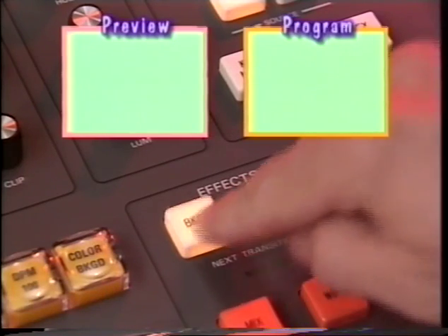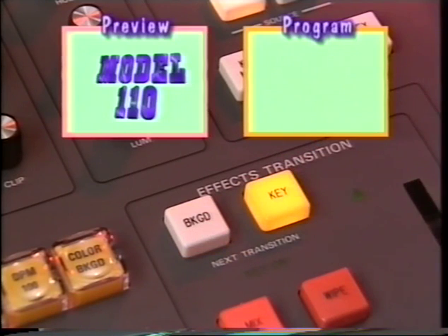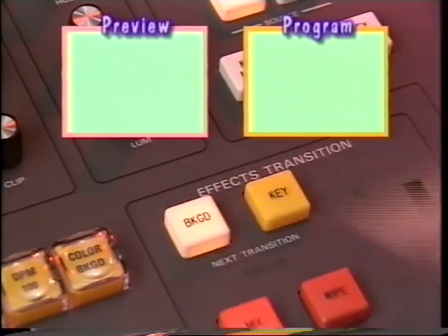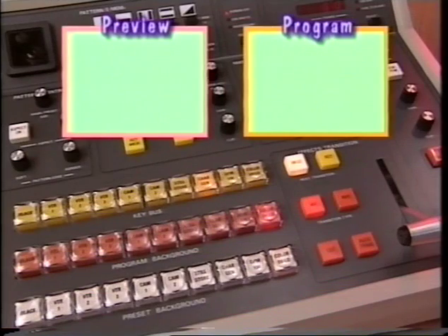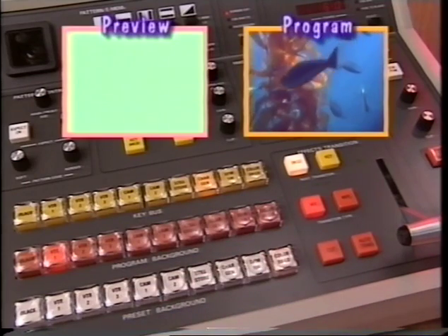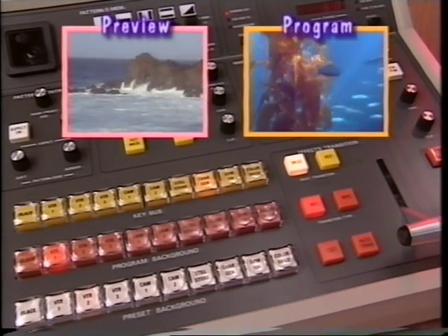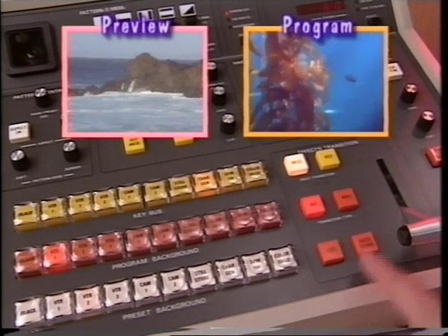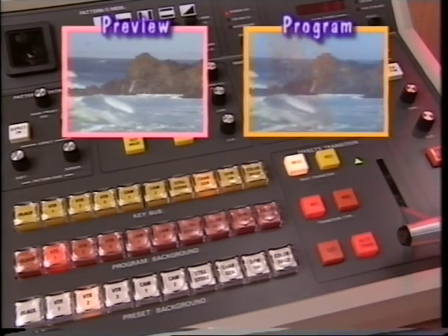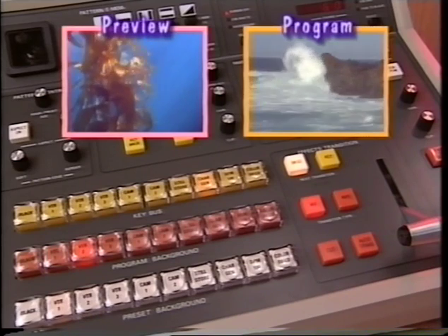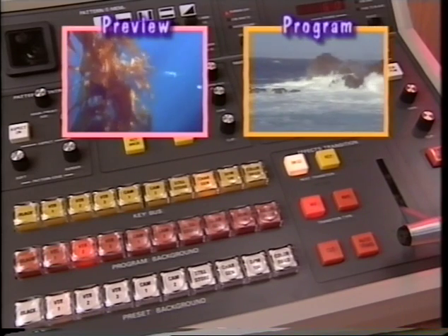The background and key push buttons in the effects transition group select the mode of the transition panel. Background causes the next transition to take place between video selected on the program background bus and the video selected on the preset background bus. When a background transition is in progress, the program output becomes a mixture of the video signals from the 2 background buses.